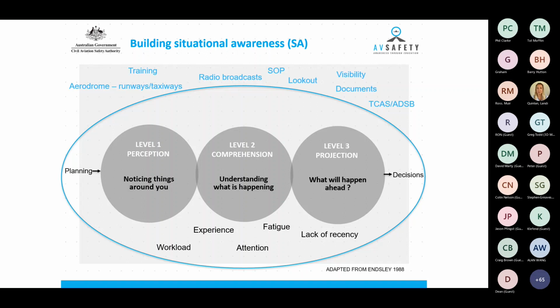Some psychologists say, through research, just for your information, that sound is more likely to be responded to correctly when you're under stress or in situations of high workload. In those situations, you're more likely to miss sighting or seeing something that might be critical for the operation of your aircraft. So if you need to rivet your attention, psychologists found that sound is more likely to do that, and that's why aircraft manufacturers build in things like audible alarms and warnings for things like aerodynamic stalling, to warn you that the aircraft is about to stall.